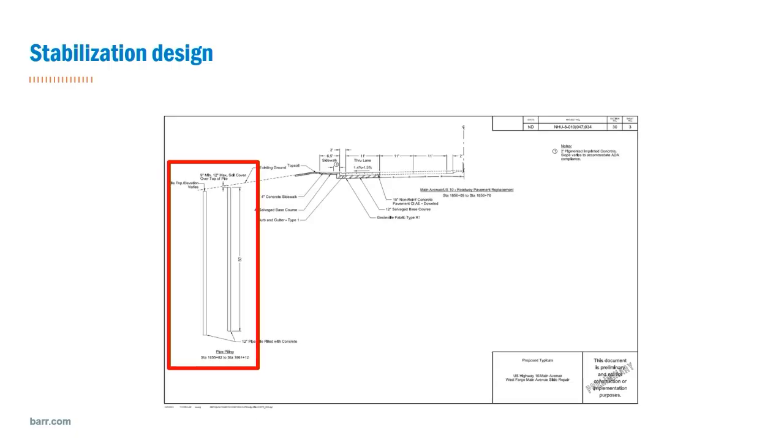The piles were approximately 50 feet long, and if we go back to the cross-section, the till layer, which is really the hard layer in which everybody drives the piles to in the region, is about 80 to 85 feet down. We only drove these piles 50 feet down, and the benefit of doing that numerical analysis is that we were able to shorten the piles such that we didn't need to weld sections on the piles, and you could deliver these piles to the site on a standard semi-truckload.